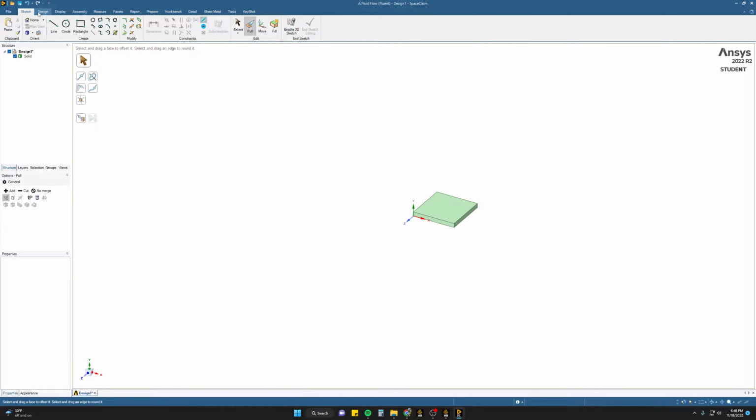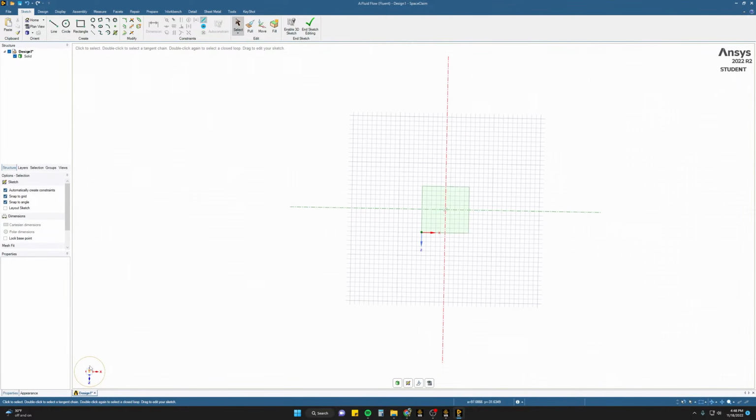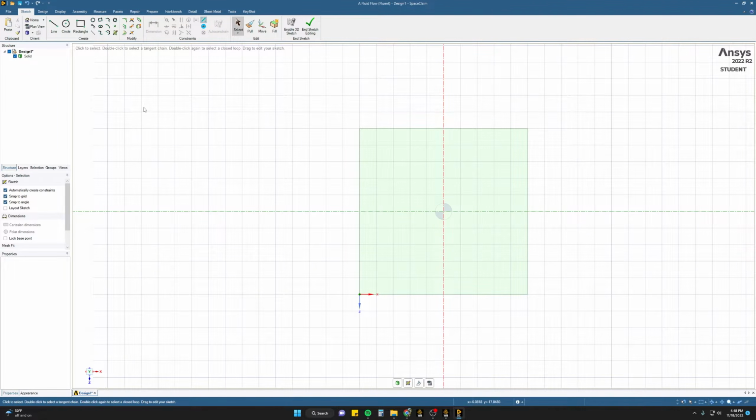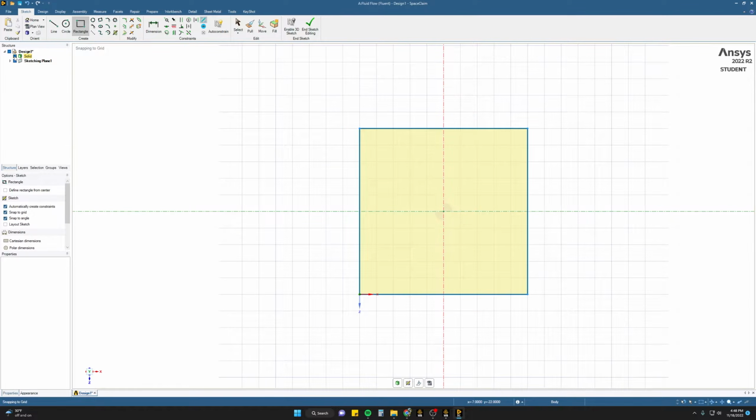Next, we'll create our heatsink. So we'll go to the Design tab, click Sketch, and sketch right on top of that chip that we just created. We can use this little Cartesian coordinate in the bottom left corner to change our view. So we'll click on the Y so we can look top down, just to give ourselves a better reference frame here. And we'll create another rectangle, same size, so another 10 by 10 millimeters, and deselect our chip underneath just so we're looking at our heatsink.